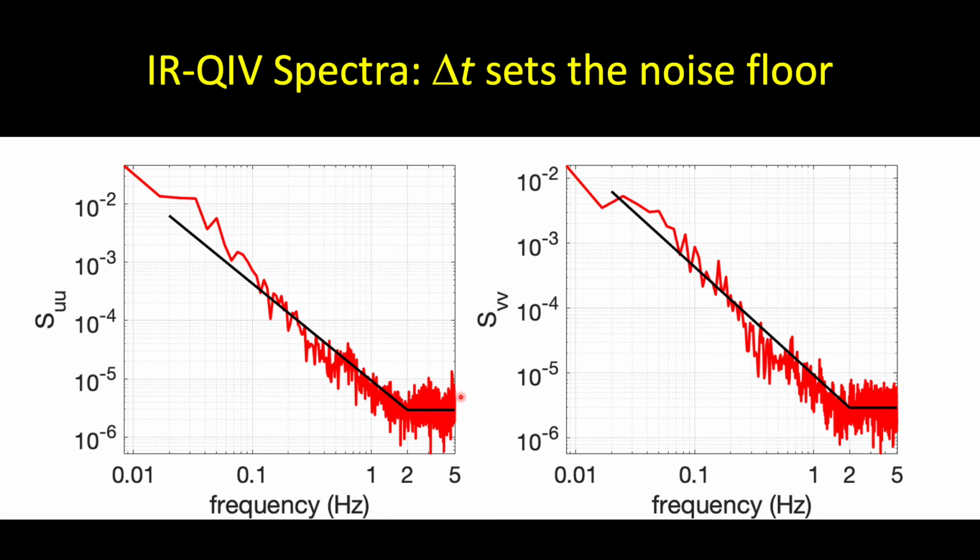delta t scheme that would let us play with delta t as a function of displacement. We obviously need delta t to be big enough to have a sufficient displacement, to have sufficient accuracy for the technique, but not so big a displacement that we have decorrelation. And so a dynamic algorithm in these oblique imaging techniques would be a very powerful way to extract both higher information at higher frequencies, as well as ensure sufficient accuracy at the slowly moving regions of the flow.